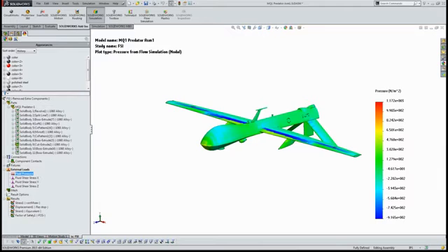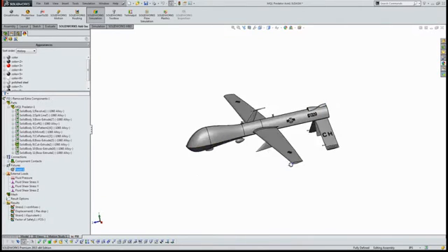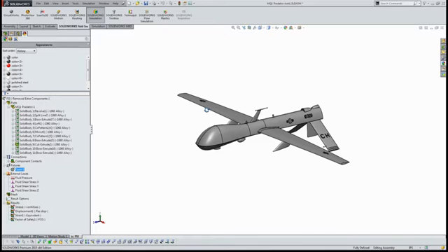And the meshes are completely different, right? The mesh from the flow solver is completely different from the mesh from the FEA solver. The types of meshes that are adequate in both cases are very different. So it does a 3D interpolation to get the correct pressures on here. I said this is a very basic setup. I just fixed this at two places, at the center up here and this back face. And now I can take a look at the stresses.